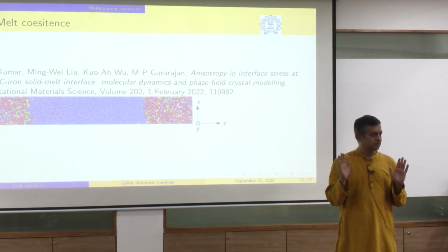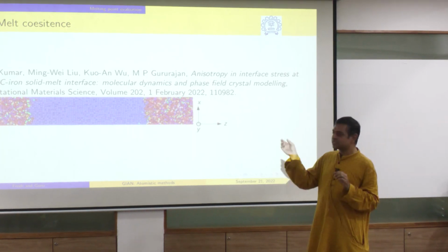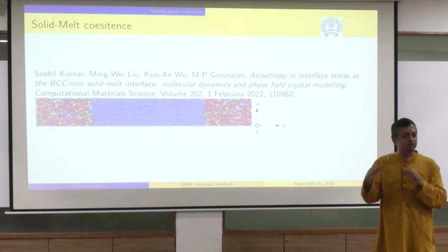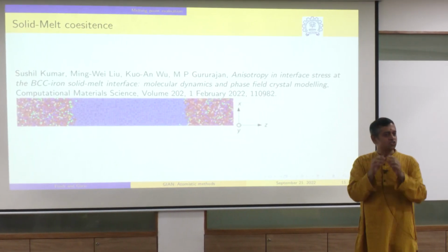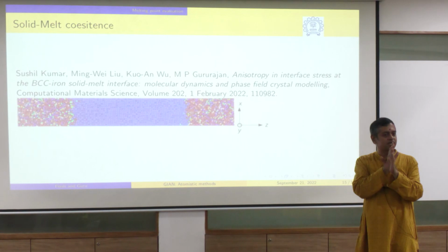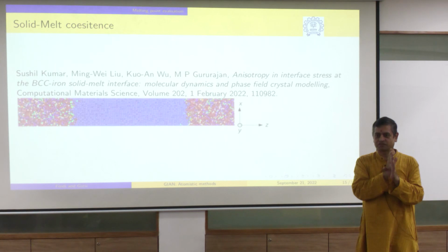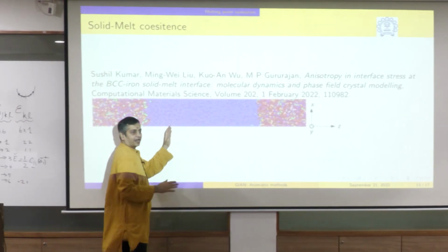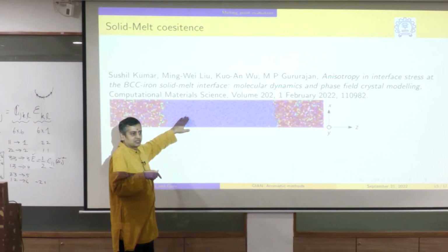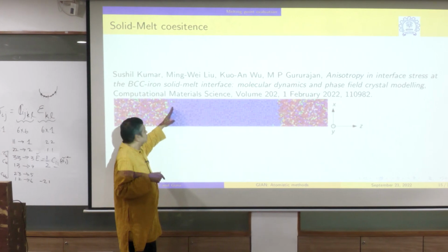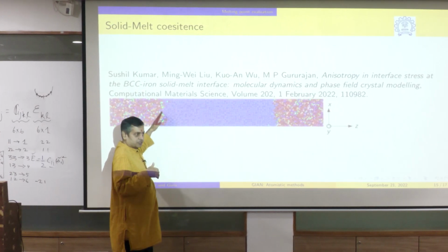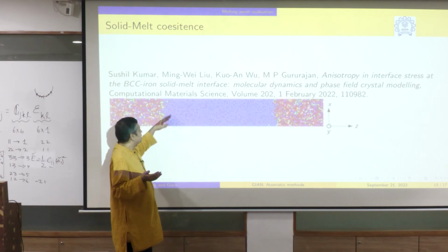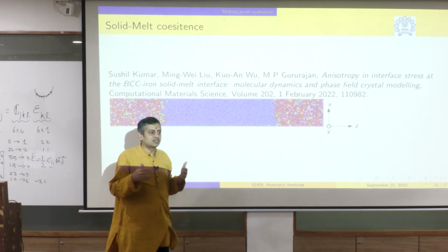but this is sufficient for us to know in which range the melting temperature lies, right. Once you know that, yesterday Ferdi drew that curve, right, solid, liquid, the free energies. So the point where the solid and liquid free energies are the same is the melting temperature, that is the thermodynamic definition. Now, if I take such a system coexisting and keep it below melting temperature, what should happen? The solid will grow, because you are below melting temperature, it will try to eat up some of the liquid and reach its equilibrium, which means the potential energy and kinetic energy in the system will change.